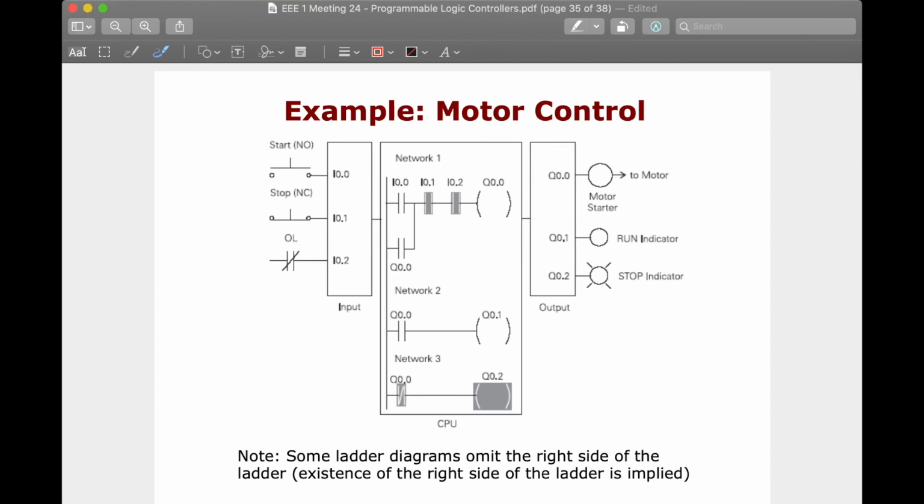Okay, so let us actually interpret what happens on the CPU. So here we have an OR operation between the push button one, which is normally open, and the coil 0. And then you have here the normally closed push button stop and the normally closed overload protection contact. So that means this is always shorted. So you can imagine that there's like a line here, normally shorted. So that means that it is high. By default, it is high.